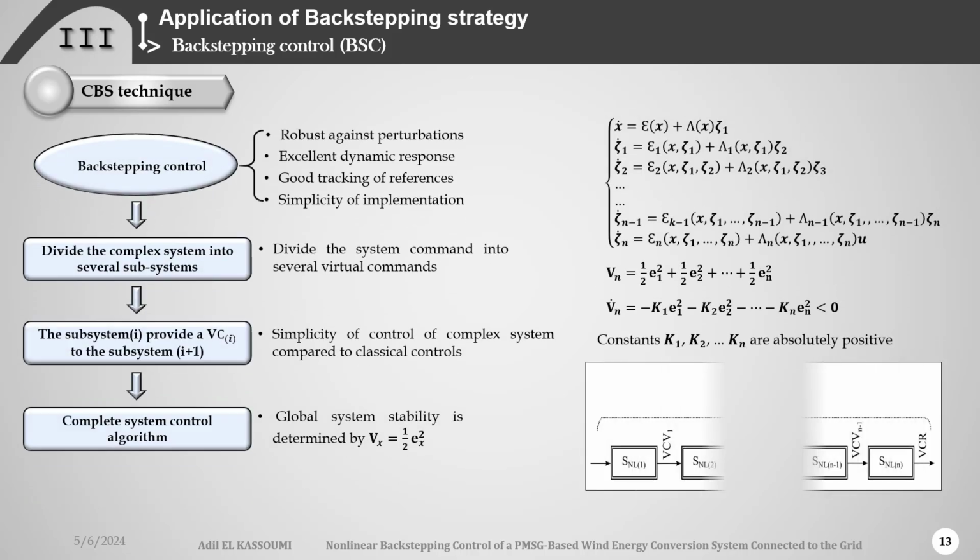The backstepping controller is widely used in the literature due to its advantages. The concept of backstepping control consists in decomposing the complex system into several subsystems. In each step, the virtual control of the subsystem is calculated to be used as a reference for the next subsystem until the control law of the complete system is formed. Global stability is determined by the Lyapunov function.